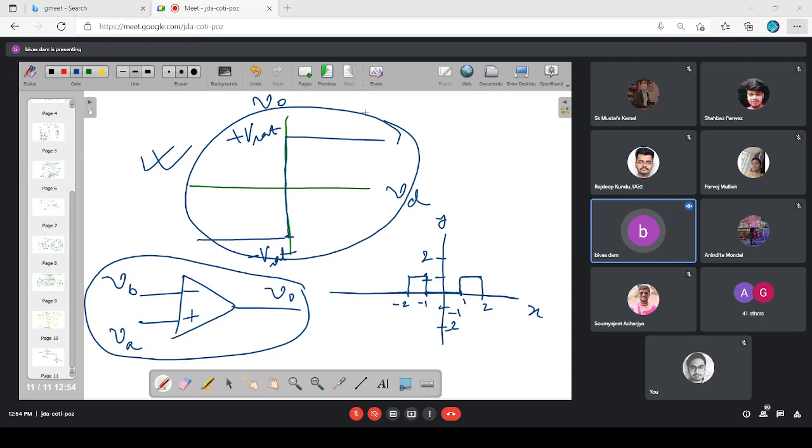So that means here, using this circuit and these characteristics, we are basically using this circuit as a voltage comparator, comparing two input potentials. Depending upon the relative nature of the two input potentials, the output is either plus VSAT or minus VSAT. So by observing the output potential, I can readily infer the relative nature of the two input terminal potentials. So this application of the operational amplifier, is there any feedback here? No, sir.